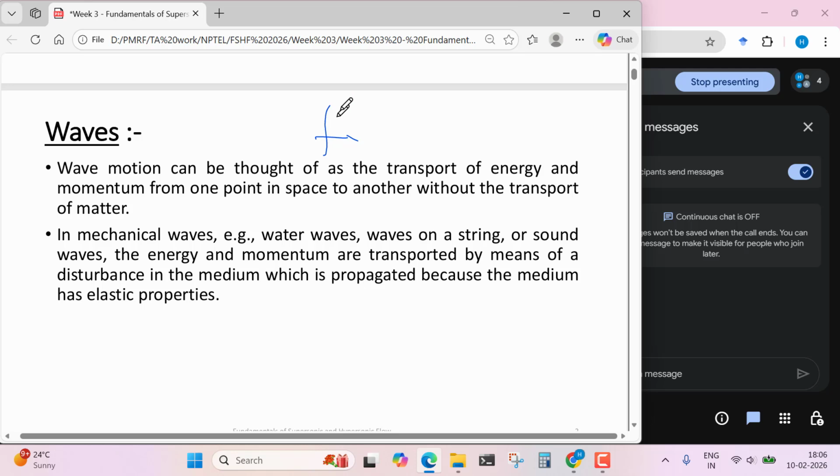If you have solved the normal shock, you might have seen that if a normal shock is moving, let's say the flow here is at rest, equal to 0, and one shock is moving here, then the velocity behind this shock will increase. So it means that its energy and momentum are increasing. So the shock can be seen as a transport of energy and momentum.